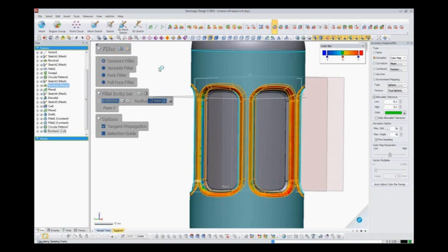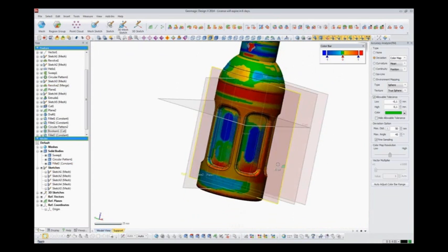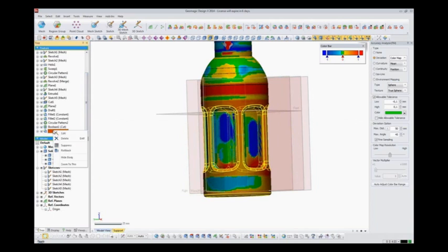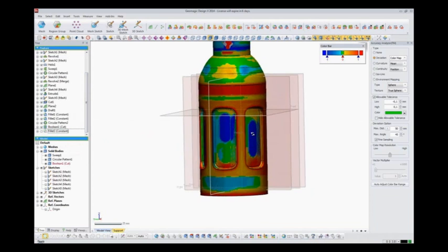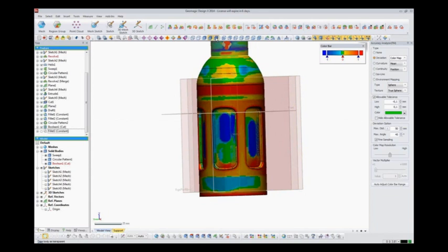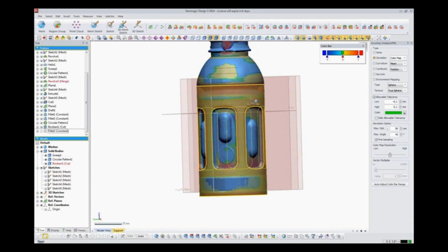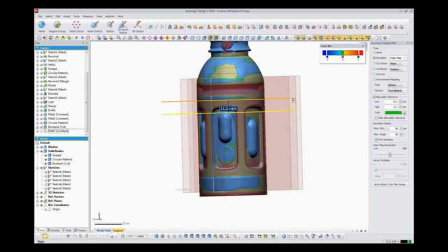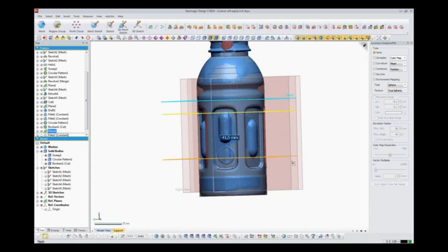The bottle is heavily deformed. We did forget one thing. We have an inset here. So before that filleting, again the parametric comes in handy. I can just roll back before that fillet, and then I can have a look at the bottle where this inset starts. So I can just drag this plane up there, and I can use the split face function.